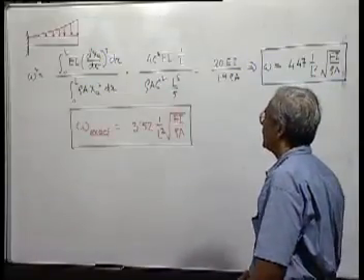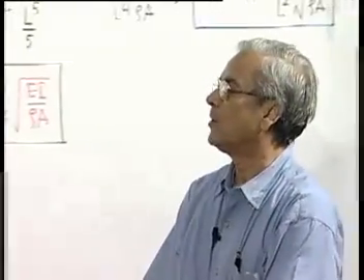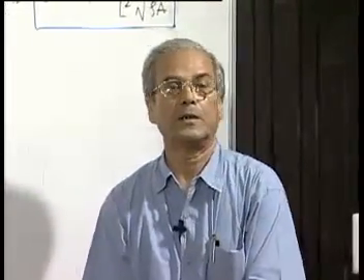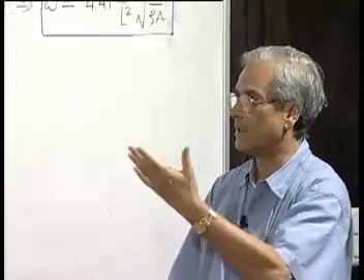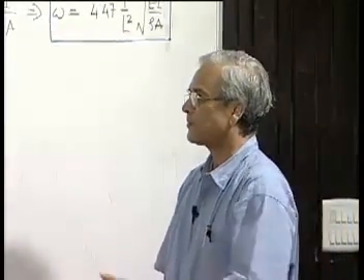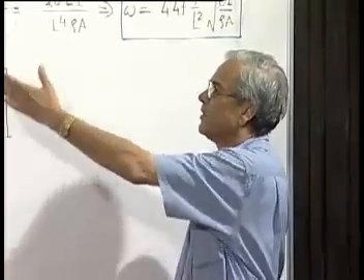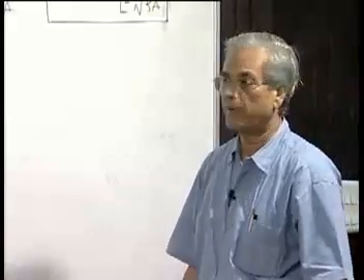So I think this will be enough for the time being, but we have to now keep in mind whether it is possible to find out the higher mode or higher frequency. In all these cases, this Rayleigh's principle is valid in case of fundamental frequency, as you know. So therefore, we are all the time assuming something for the first mode deflection.